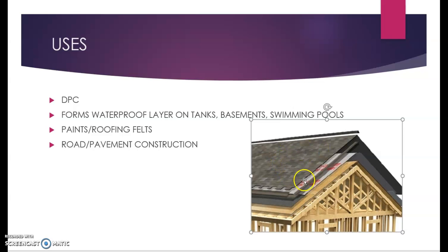Now what has happened in Goa is that it is mandatory to provide Mangalore tiles for at least a certain percentage of the roof. I think around 25% needs to be sloping, because the government wants to maintain that heritage look. Also, because ours is a heavy rainfall zone, we don't want water to stand on the flat terraces. That's why we provide a part of our terrace as sloping, so that the water easily drains out.